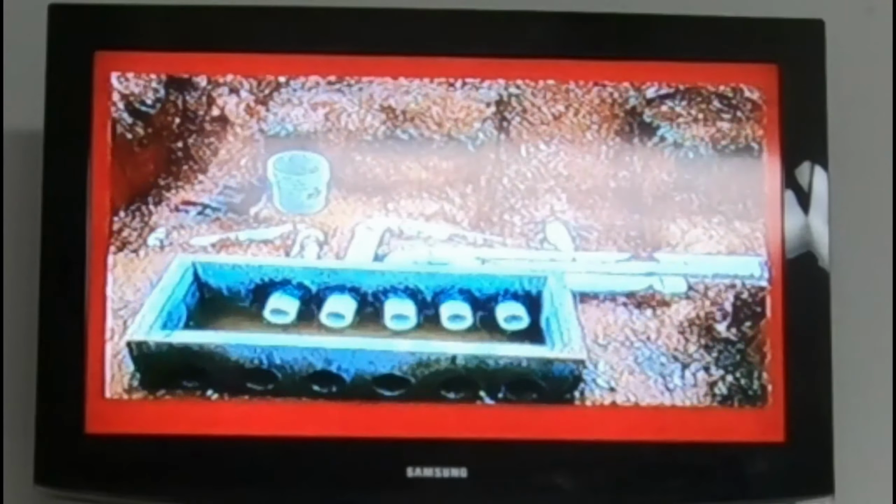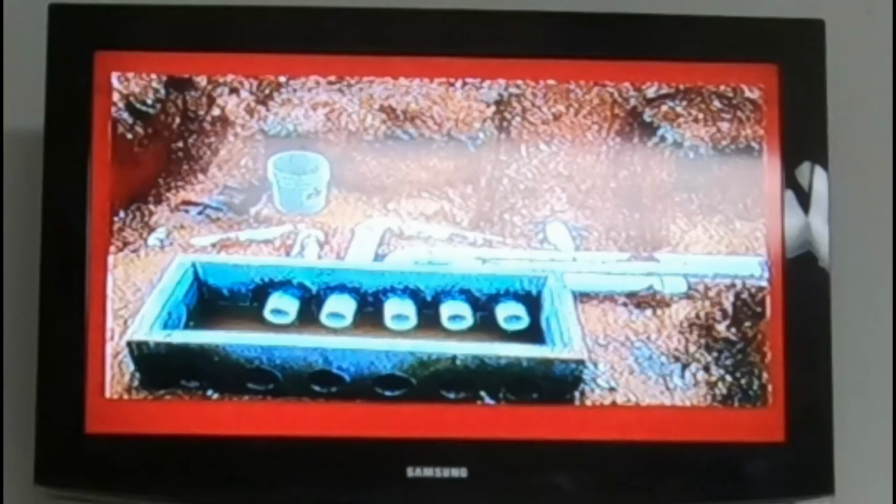Absorption trenches for a distribution box system can be installed level on a uniform change in grade of no more than 4 inches of fall per 100 feet. This is the only exception to the absorption trench leveling requirement. The department's technical review committee may approve other distribution devices for use with conventional septic tank systems.